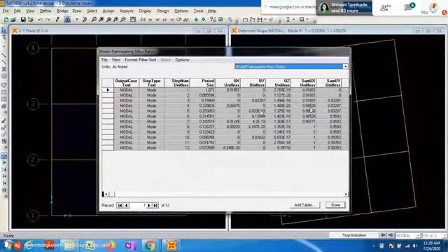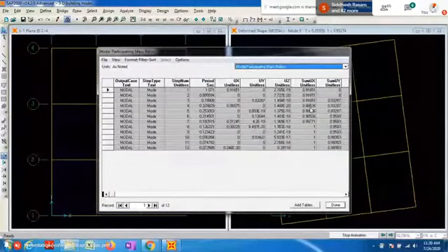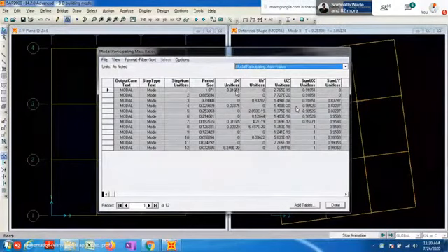Now I will note particular time periods, because in the time history analysis we require them. Along the X direction, just remember, this is a translational mode. The time period is 1.07. In the X direction, the next translation mode is this.